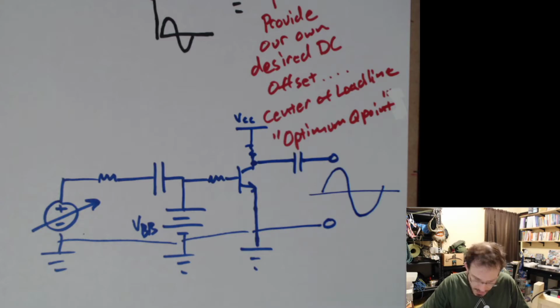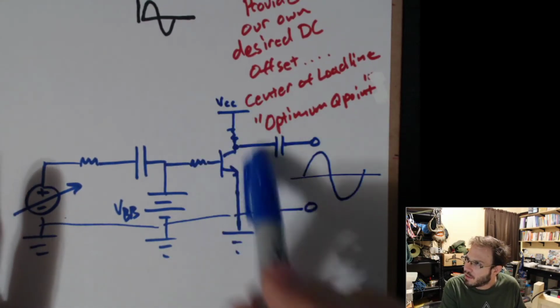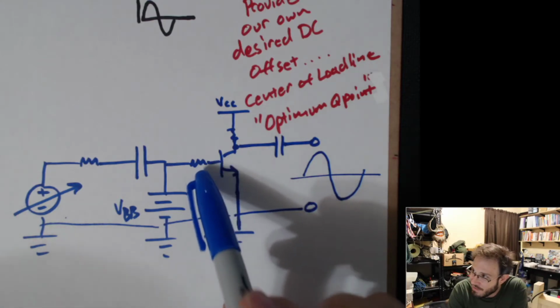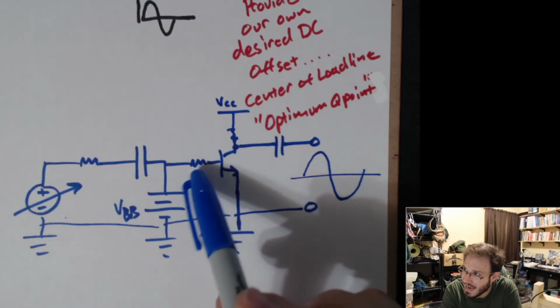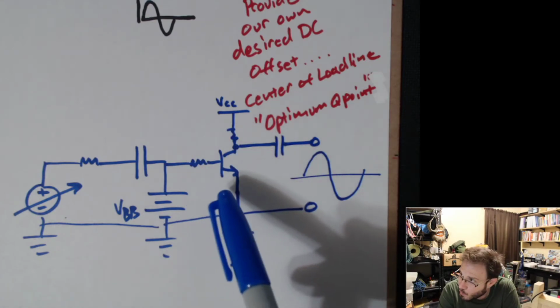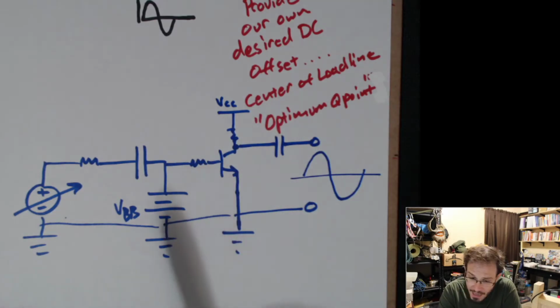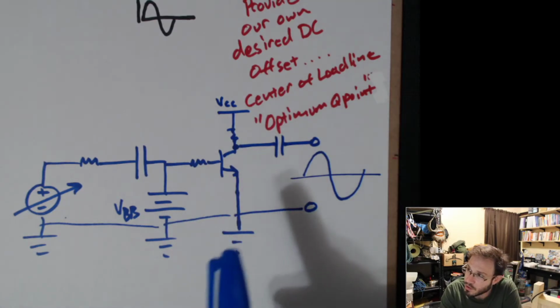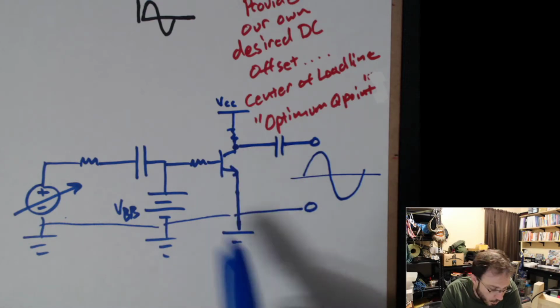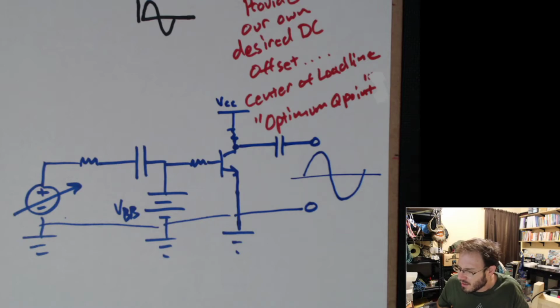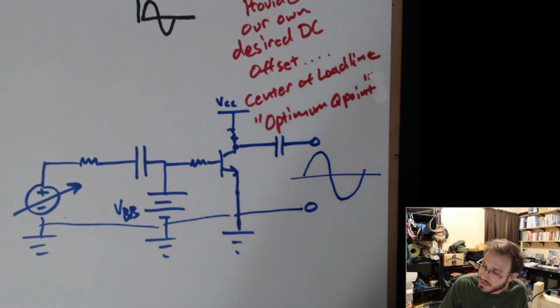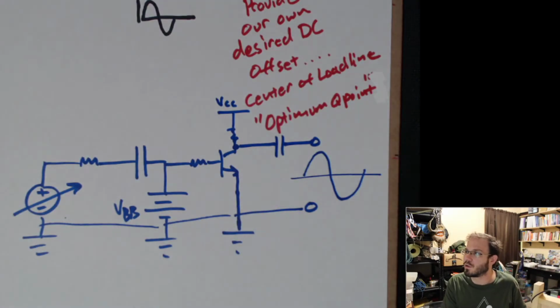Okay, now for reasons that we spoke about, the base bias transistor circuit is not a very good circuit because of its dependency upon that value of beta. And for that reason, we will be using a voltage divider bias. Now, I'm going to go ahead and do the full solution for the voltage divider bias common emitter amplifier next class, where we put all of these principles together and solve for what we're most interested in as far as the amplifier is concerned.